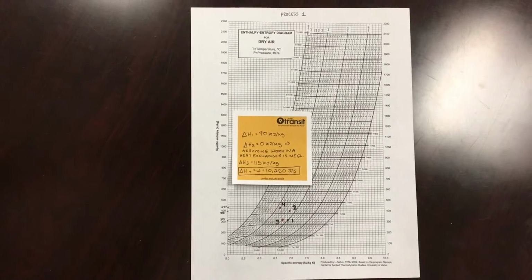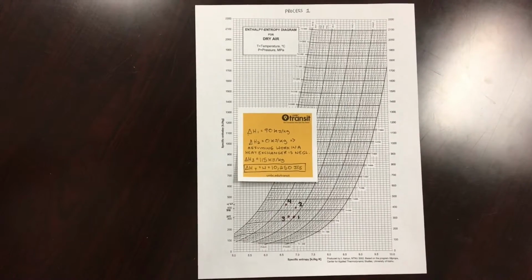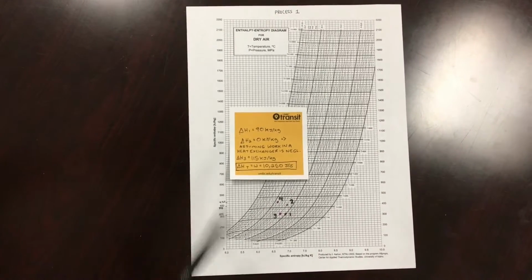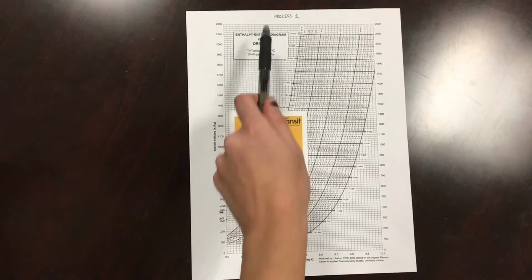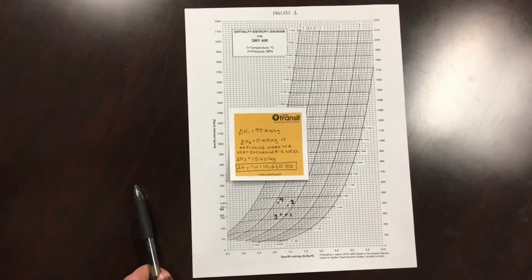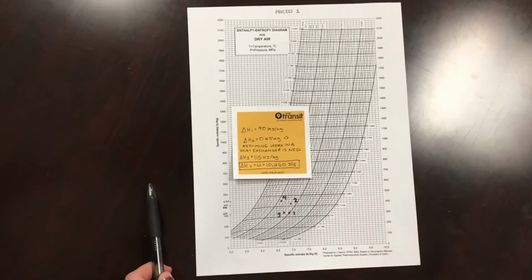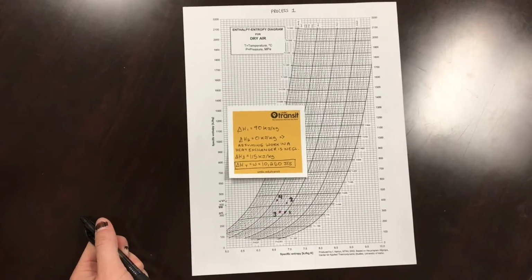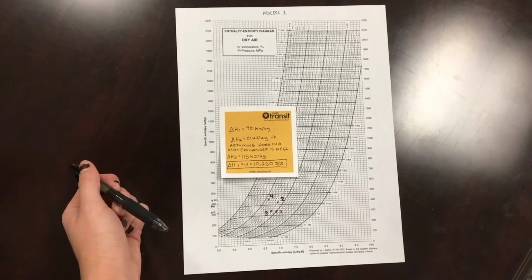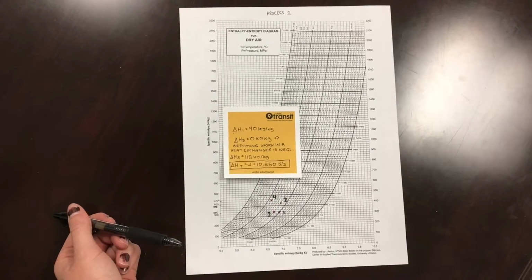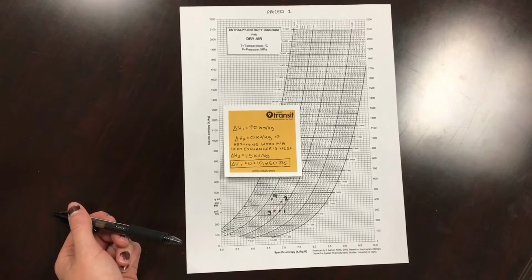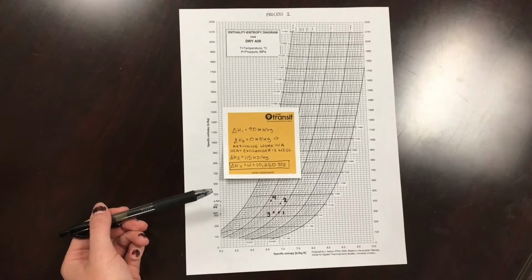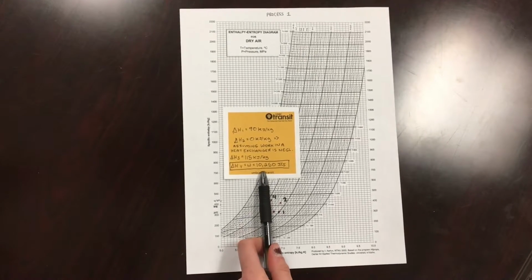Once I had my ideal gas calculations, I went ahead and compared my value for total work using an enthalpy diagram. Before I began, I had to convert my values because this diagram is in megapascals and degrees Celsius rather than Kelvin and kilopascals, which my original question was posed in. I calculated my delta H values using this diagram and the 4 points that correlate to the PV diagram data points. My delta H2, which corresponds to the area of work 2, was approximated to be 0 because I assumed that work in a heat exchanger is negligible. Once I had my 3 delta H values, I summed them up to get total work and got a final value of 10,250 joules per second.